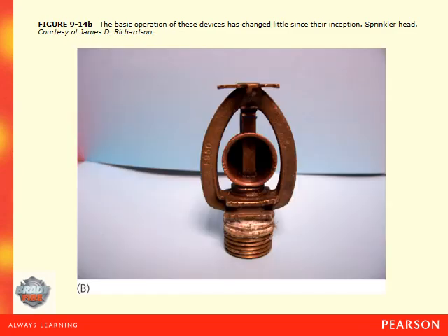Sprinkler systems have sprinkler heads. Here is a picture of a typical sprinkler head. This sprinkler head has a fusible link, meaning something metal in there that you can see that will melt when the temperature in that room rises to a certain preset temperature, which melts the metal and causes an opening in the orifice of the sprinkler, allowing water to escape, thus being applied to the fire.